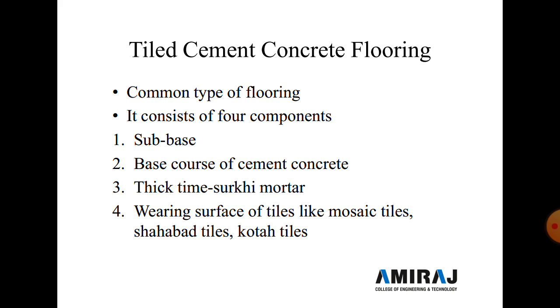And fourth point is the wearing surface of tiles like mosaic tiles or Kota stone. So then the next process is to make a wearing surface like tiles work. Before laying the tiles like mosaic tiles, Kota stone tiles, etc., the neat cement slurry is sprayed over the bedding mortar, and then tiles are laid flat, gently pressing them with a wooden hammer and leveling it properly so that water is removed easily.